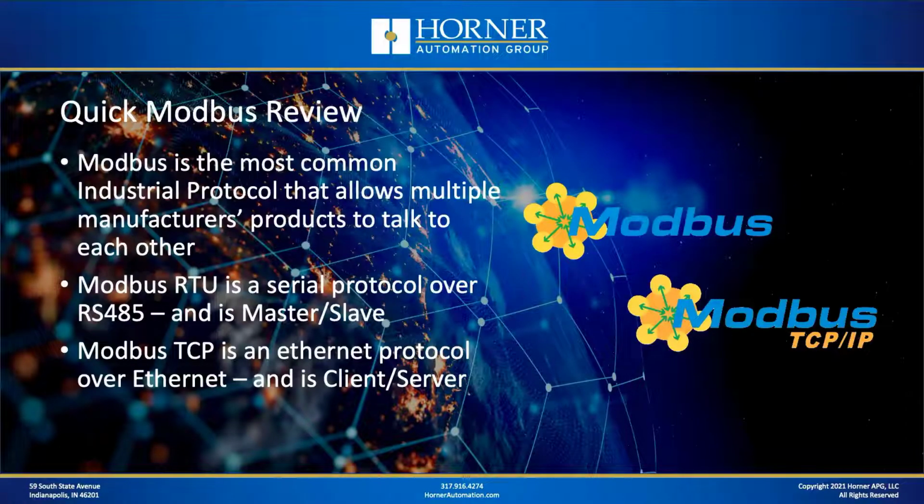Okay, quick Modbus review. Modbus is the most common industrial protocol that allows multiple manufacturers' products to talk to each other. So if you've got two devices from different manufacturers and you want to apply them in the same application, Modbus is what they would call the lowest common denominator, or the most common protocol for allowing those devices to share data. Now, Modbus is applied a few different ways.